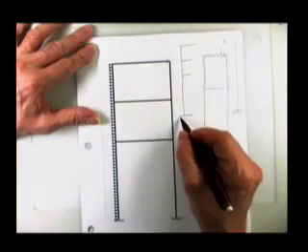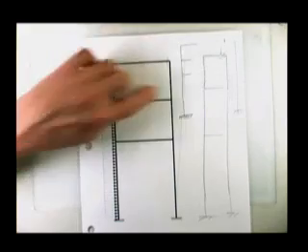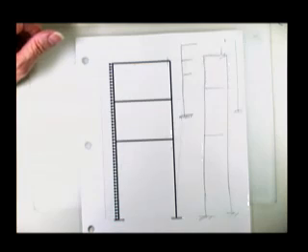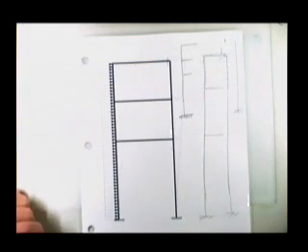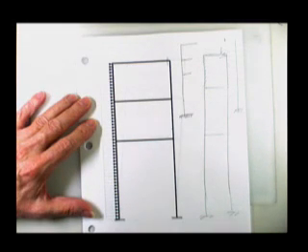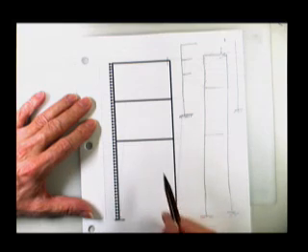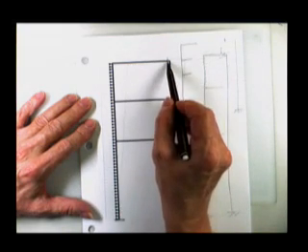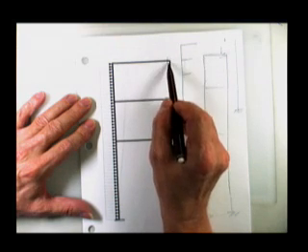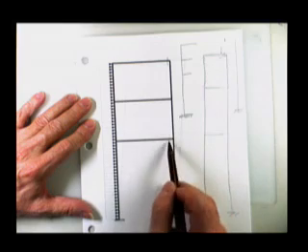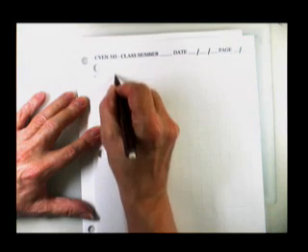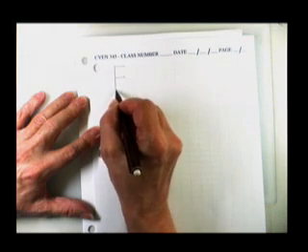They don't look like they'll fall down because they look like diving boards where someone has put some little stick outs on it, and another diving board. Another possible, incidentally, how I saw how many degrees indeterminate it was, anytime you cut through a beam, you cut through 3 things: axial force, shear, and moment. So you released 3 constraints, 3 constraints, and 3 constraints. Here's another perfectly good statically determinate structure for purposes of analysis.